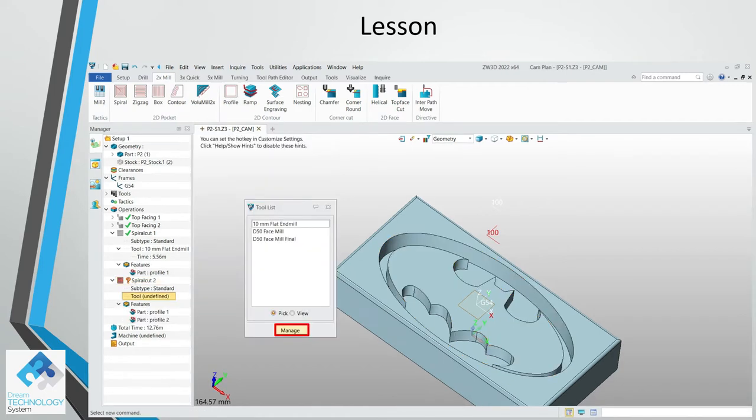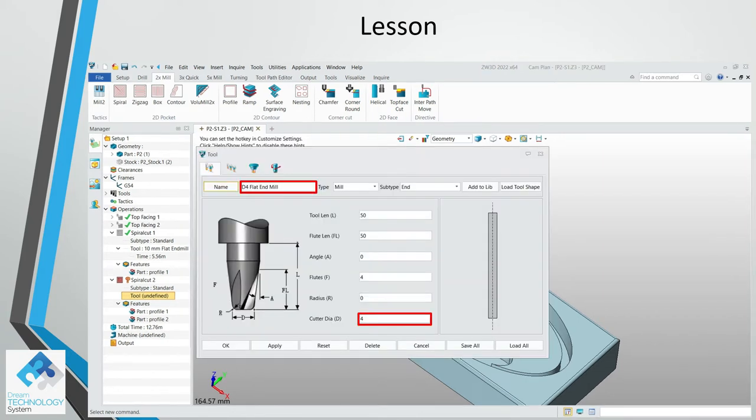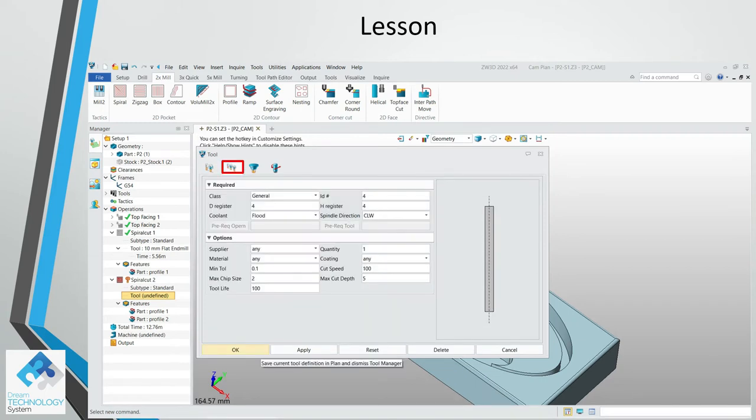We click OK. We need to change the diameter of the tool. We need to change the diameter to 4 because the gap is about 6 mm. If you go through the previous drawing process, then you know that the gap is 6 mm. I want to leave 0.5 on the wall. I could choose diameter 5, but to prevent it from getting stuck with the chips, I choose diameter 4, so that at least we can see how it's going to cut with the 0.5 balance. So we put diameter 4 and we put the tool number.